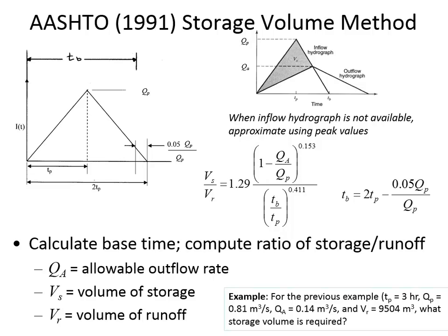All you need is to make it big enough to hold the water difference. Like the project you did last semester, you didn't make your storage reservoir big enough to hold all of the water used in the town during the whole day. You only make the storage pond big enough to handle the difference between the inflow and the outflow, not so big that you assume there's no outflow during the entire day.